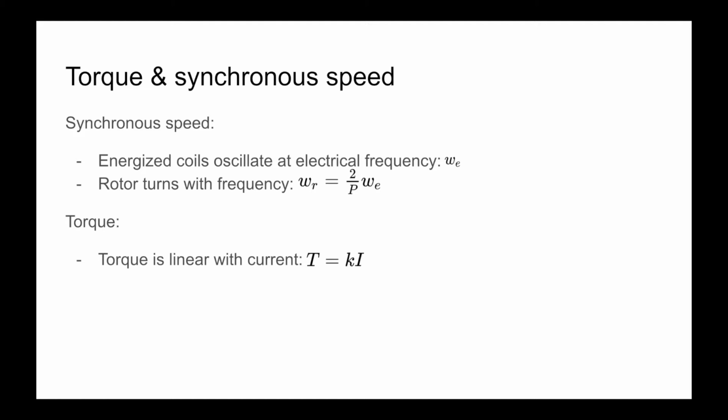I mentioned previously that a motor with more poles will have more torque and less speed, and this is where that statement came from. For constant power and all other variables, including things like size being constant, more poles will cause the motor to operate at a slower speed and thus output higher torque. This is also why high torque motors often have lots of magnets.